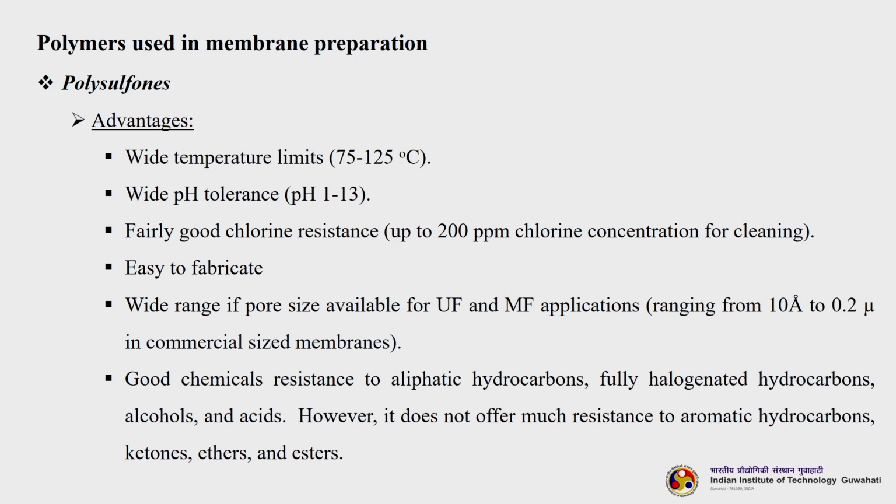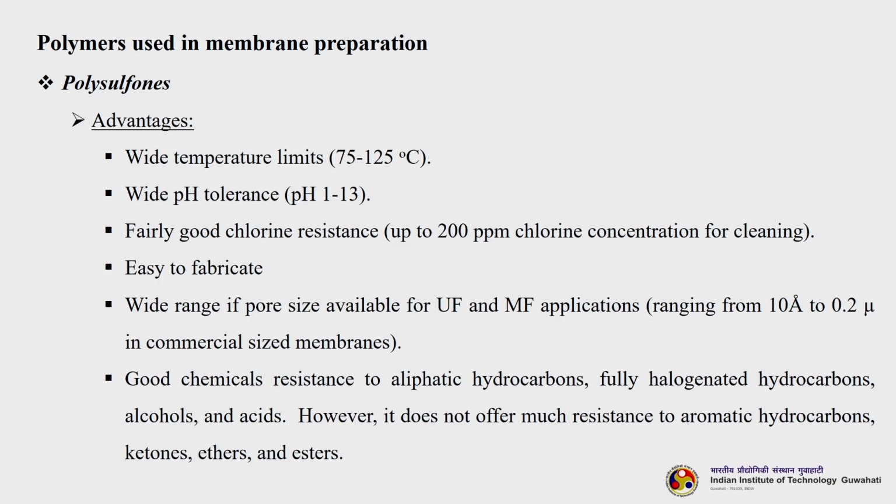So, for cleaning purposes, this type of membrane will have no problem while it deals with chlorine, and it is easy to fabricate, with a wide range of pore sizes available for ultrafiltration and microfiltration applications. So, we can easily prepare either microfiltration or ultrafiltration membranes using polysulfone material.